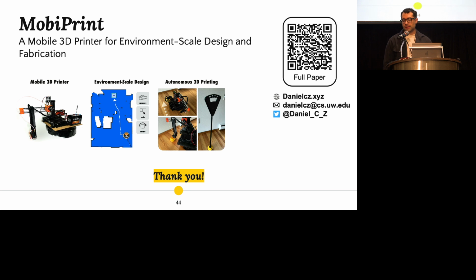Yeah, beyond, I think bed adhesion is generally a problem that people have with 3D printing, right? So tweaking your first layer properties, the geometry, your brims and so on, that's stuff you can do. But I don't know if I thought about editing the surfaces; I almost thought of how I can prep the surfaces. For example, I do have clearance underneath the robot. So if you wanted to, you could almost put a heated bed, so that it heats the floor a little bit, and then the robot moves forward and prints. But again, for this iteration, you have to take into account the power consumption. Once you add another heating element like that, you're going to need a much bigger battery. And we found that, at least by using PLA, which is kind of forgiving and you don't need a heated bed all the time, we were still able to get some prints off.